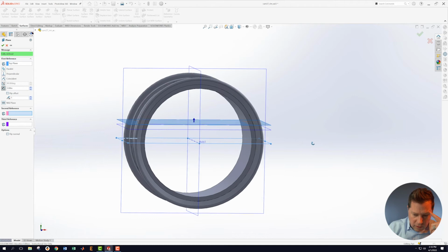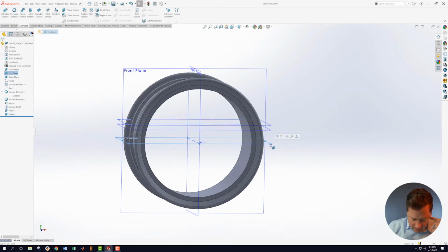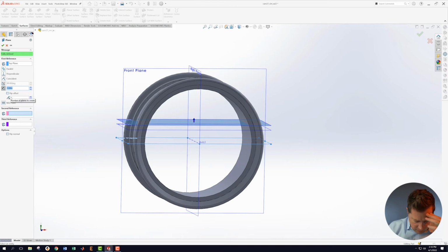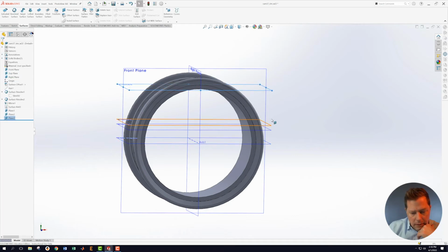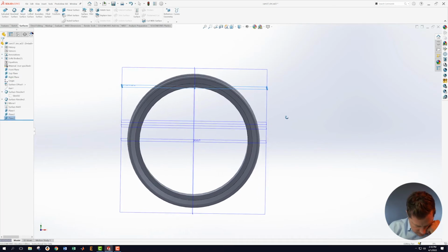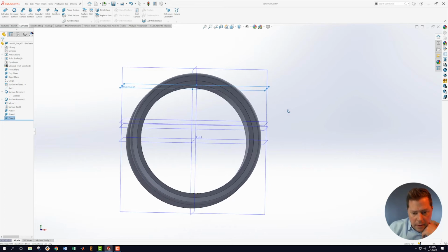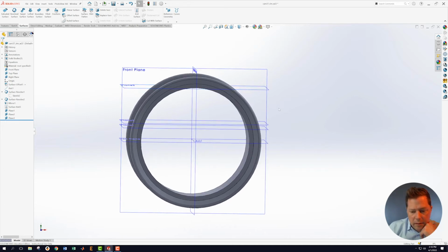Okay, great. I want to draw another cross-section on that. Accept that. And then I'm going to do another cross-section. Well, I've got to do a bunch of these things. Okay, so reference geometry plane. Now this one is 8.93. Save that. Okay, and then I need another reference plane. I should have 4 when I'm done: 1, 2, 3, and then the one I'm about to make.